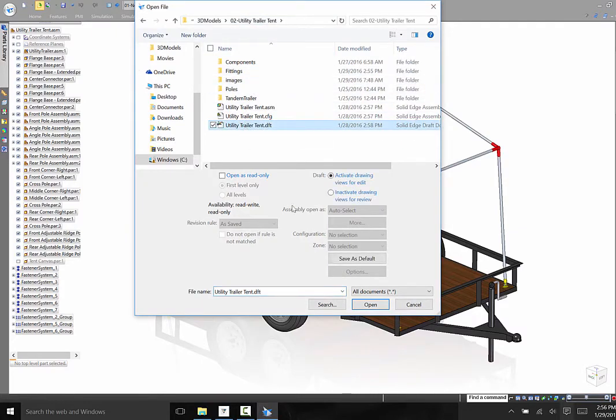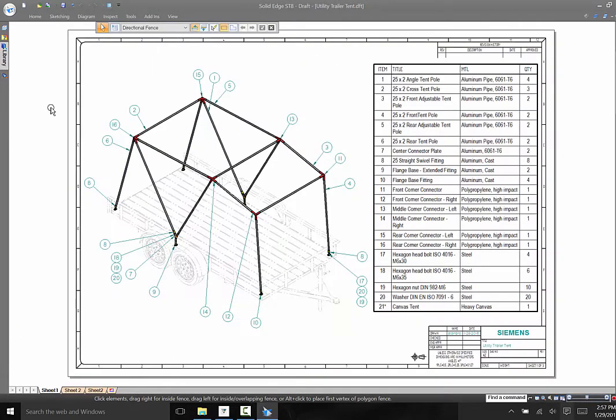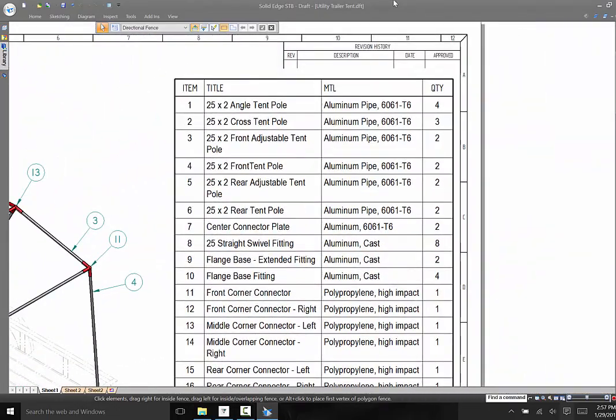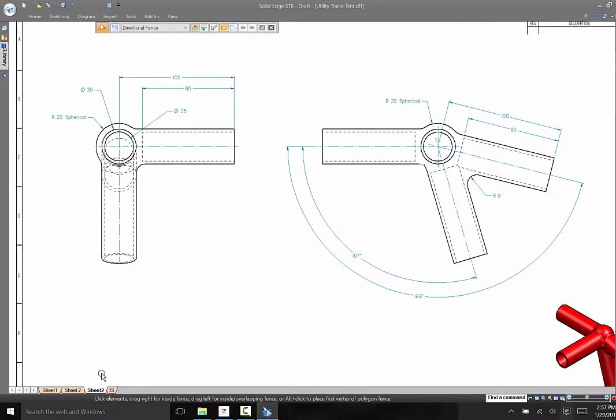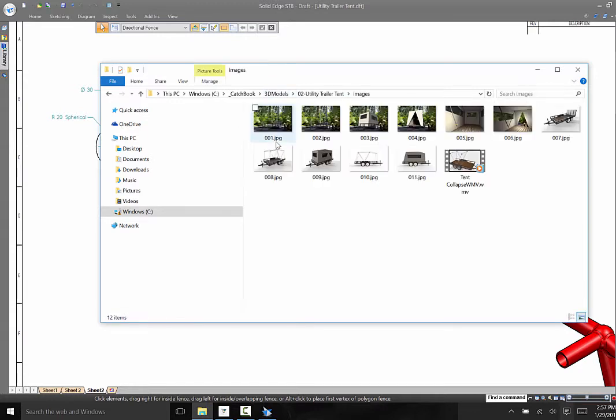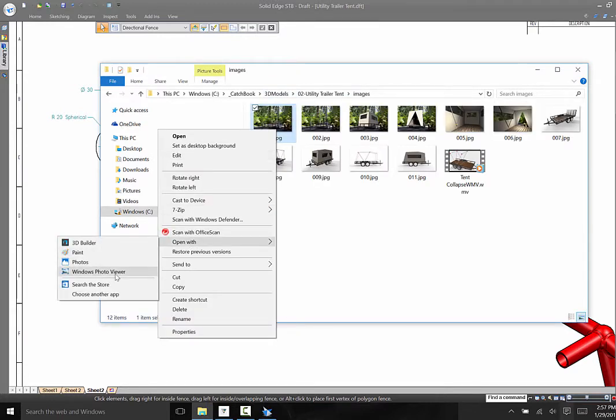Beyond prototyping, creating a 2D manufacturing drawing of the model to actually build the final product is the next step. I simply threw down a view of the completed assembly and created the parts list and balloons with just a few clicks. On this sheet is the manufacturing drawing for the connector. I took the liberty of generating photorealistic images of the design in KeyShot as well.